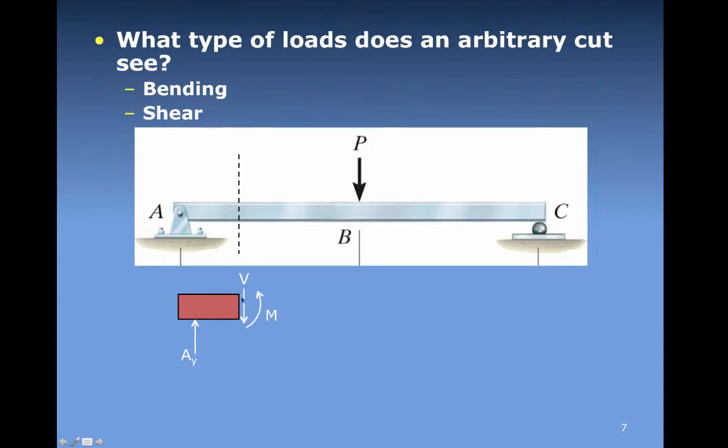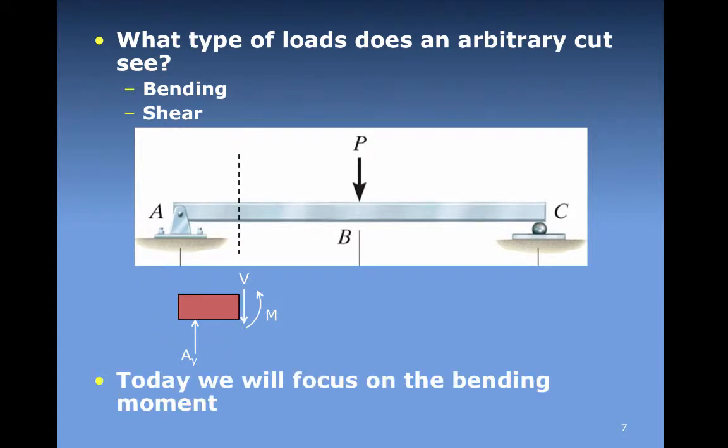And at any cut plane, we draw an internal shear force that's often denoted as capital letter V in combination with an internal moment. These are the two forces and moments that we study in beam theory, and this entire structure needs to be in equilibrium. What we're going to focus on for the rest of this lecture is the effect of this moment that's generated internal to the beam and how this moment creates stresses within the beam along this surface.